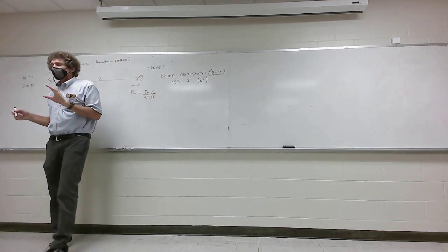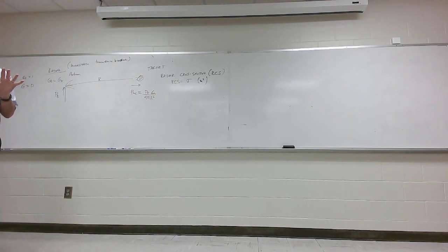Now the radar cross-section of anything is a strong function of the frequency. Let me explain this in a nutshell. If you have a perfectly metal spherical ball and you have an incoming wave on it, at very low frequencies, it has a very small radar cross-section. If you consider the cross-section of that, it would be pi a squared, where a would be the radius.